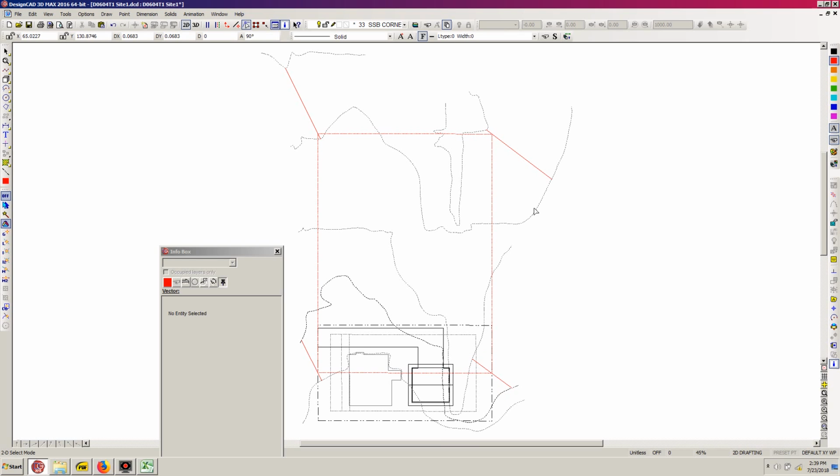From this topographic line here, that comes on down, so there is one additional 2-foot step down between this corner and this corner, and on the west side we actually have 2 full 2-foot drops. That's from this topo line to here, and then from this topo line to here.